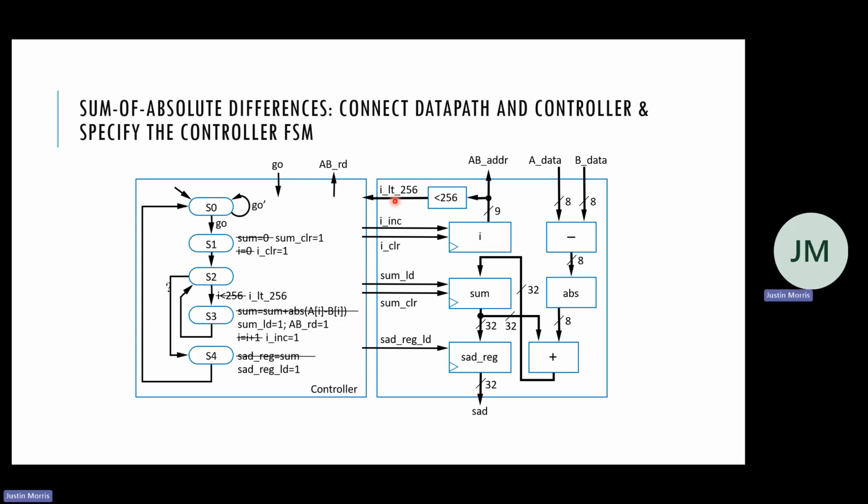And you learn from the finite state machine lab that for implementing the control, or these finite state machines, I don't need to do these excitation tables, right? I just need to have this, and I can code it in behavioral logic, right? Because you only care what takes you from state to state. Yeah, I only care about what is the behavior. If I'm in this state, this is my input, what is my next state? If I'm in this state, what is my output? Or if I'm a Mealy, if I'm in this state and the input is currently this, what is my output?